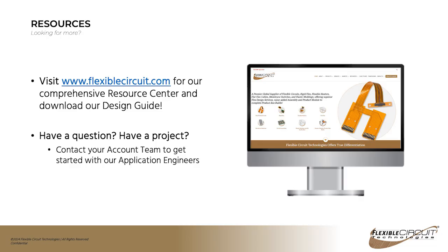Can LCP materials be laminated, and how? Yeah, there's a number of ways you can do that. If you're going to laminate with LCP as your adhesive, it can be done. Keep in mind that it's a thermoplastic, so each time that you hit the melting temperature, it's going to reflow. The temperature is typically over 300 C to do the lamination. It is a very difficult material to work with. We're seeing less and less use for that just because it is so hard to work with.